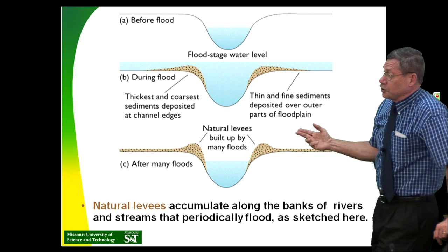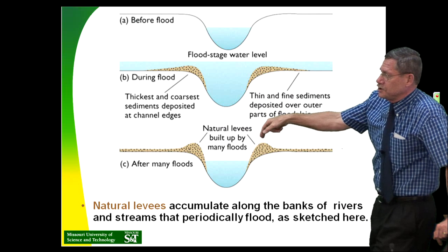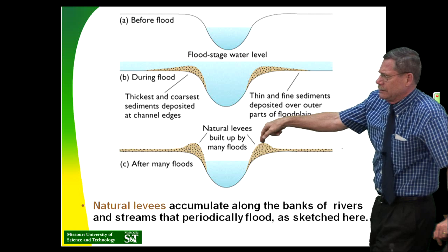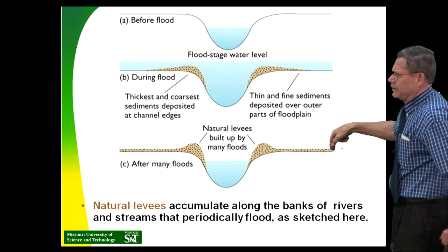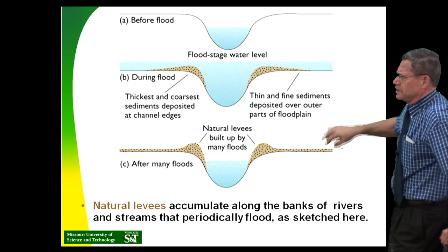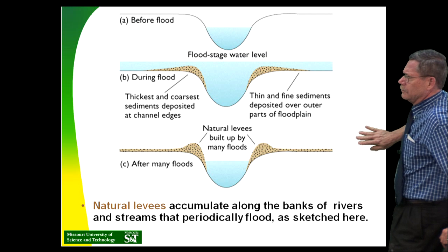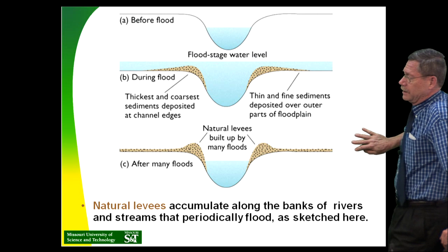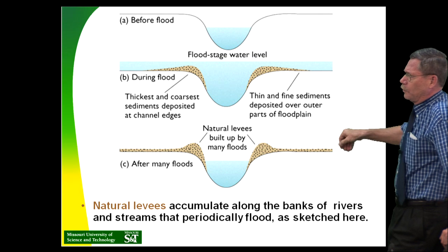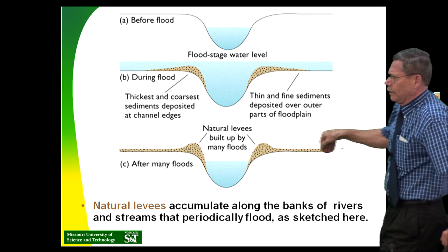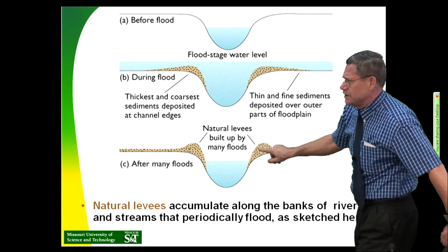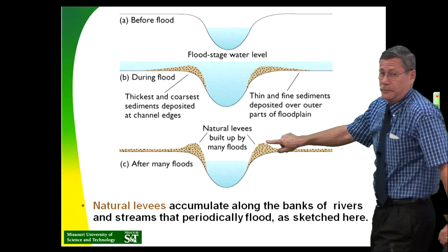So it didn't work. Now, what you could do is you could put training dikes right here, and then you'd have a setback levee back here somewhere that would protect your high-value property or developments over here. That way you don't put the one that really counts, the high value setback levee, right next to the channel, because you're putting it in a point of greater vulnerability.